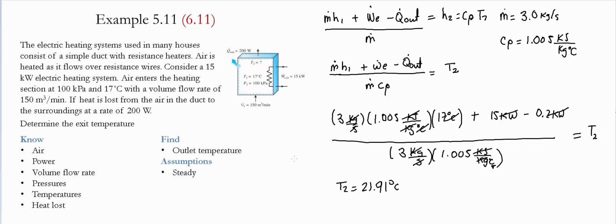Please note that the exit temperature of air is higher than the one entering the system, and this is because the power of the electrical heater is significantly higher than the amount of heat rate lost to the surroundings.